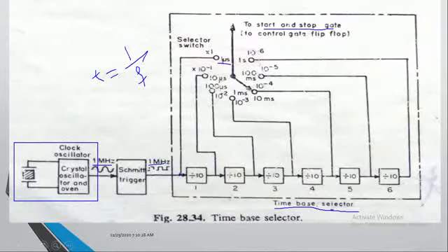At the input of the first divider, we are taking the output signal. This particular element is giving the 1 microsecond delay, and at the output of divider 1, it is dividing the 1 megahertz by 10. As it is dividing 1 megahertz by 10, it is called 10 microseconds, and another case is 100 microseconds.